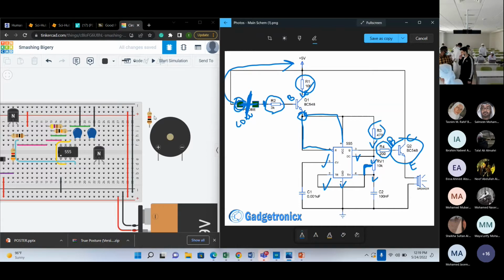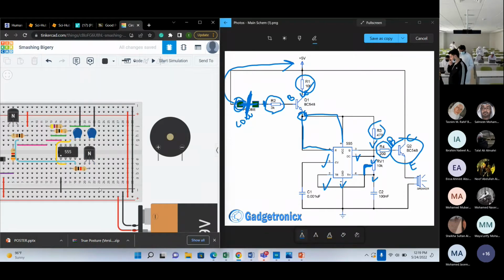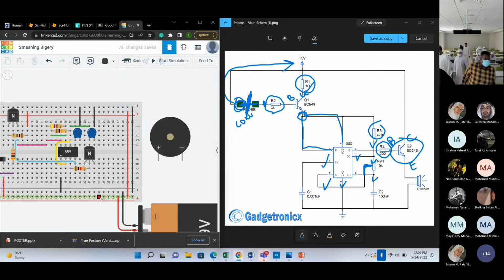What I'm going to do is take this here and rotate it. So now it's rotated. As you can see, where do I need to connect it to pin number 3? Where's my pin number 3? This is pin number 3. So now from one side, it is connected to pin number 3. From the other side, it needs to be touching the base. So I can just simply move this here, right? Will this affect me? No, this voltage line is empty, so I'm fine, right? Do you agree with this? Exactly, yes. From pin number 3 to the base of the transistor.